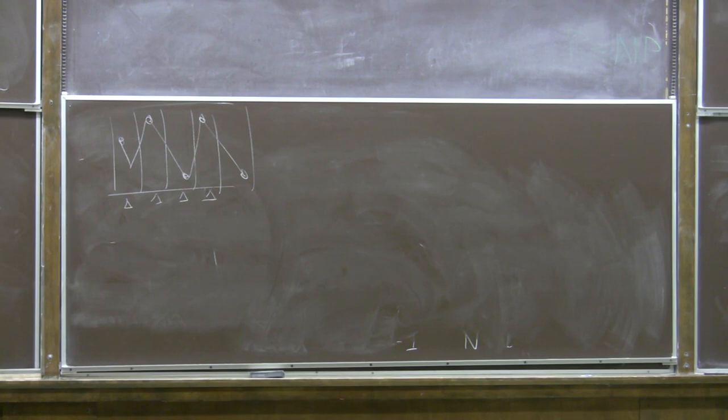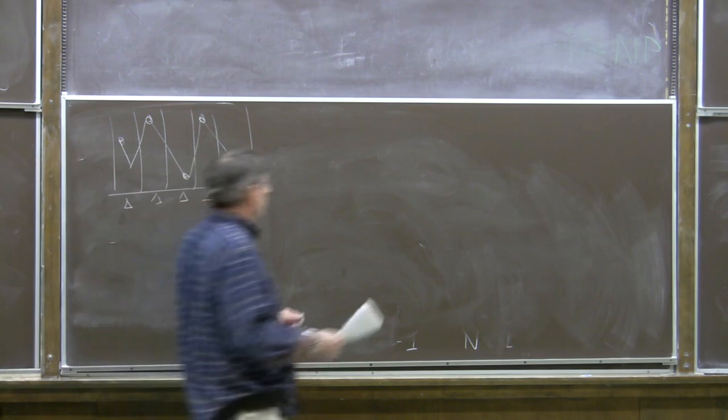So the fluctuations of the voltage itself go like the square root of that, or volts per root hertz. And so we have to integrate for a while and average the signal in order to see a signal which isn't completely swamped by the fluctuations.